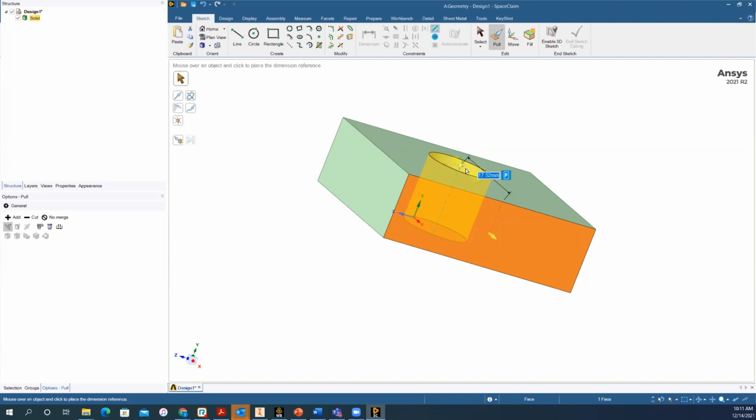This is one of the common queries that we face when dealing with support requests: I clicked on pull, but I didn't see the option to create a parameter. That's because you're not selecting a reference location from which that distance is being measured. Remember, parameters are driving dimensions. They're driving your design, so they need to be accounted for from one particular reference location.